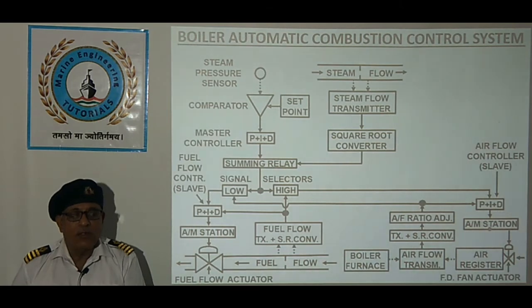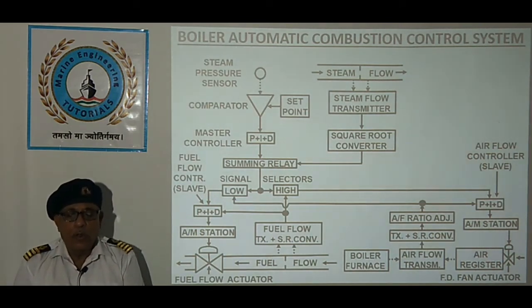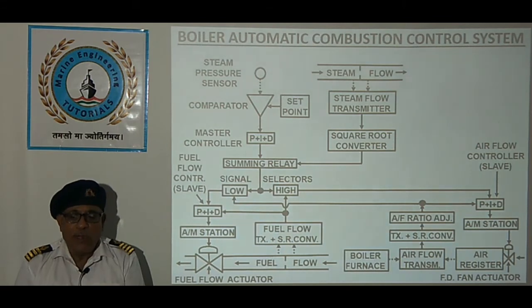And similarly, in case of increasing load, the airflow signal is increased first. In case of increasing load, airflow controller takes lead to send higher signal to FD fan actuator through auto manual station. Auto manual station is used to control individual actuators manually when automatic control malfunctions.